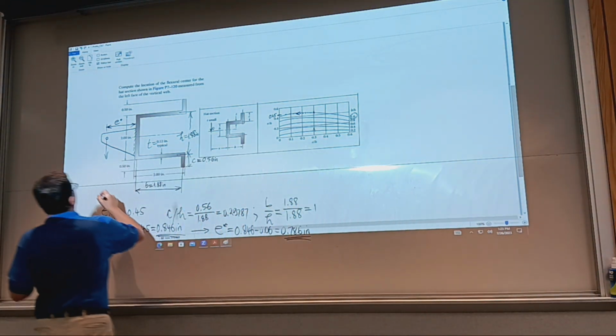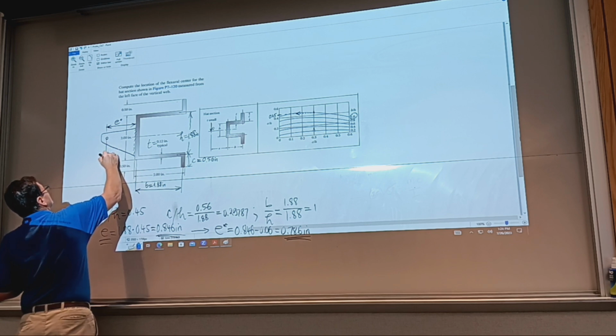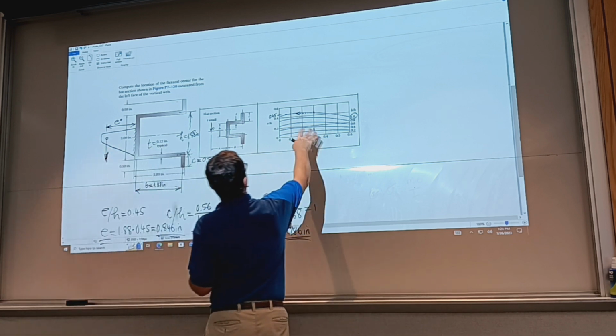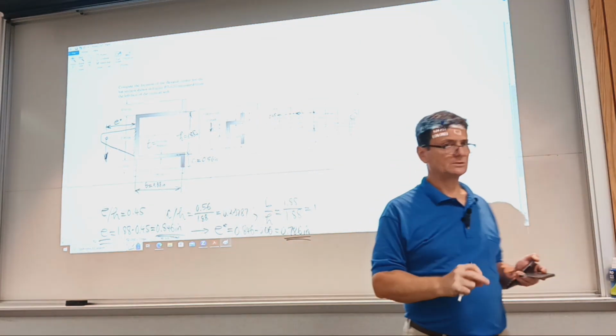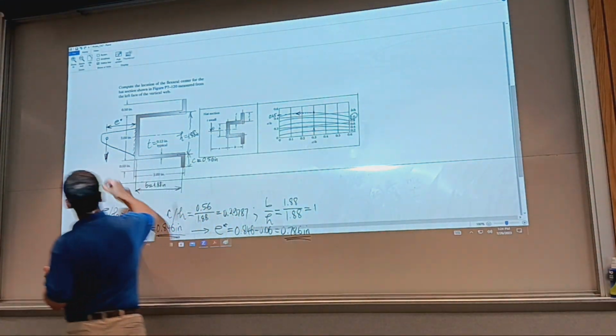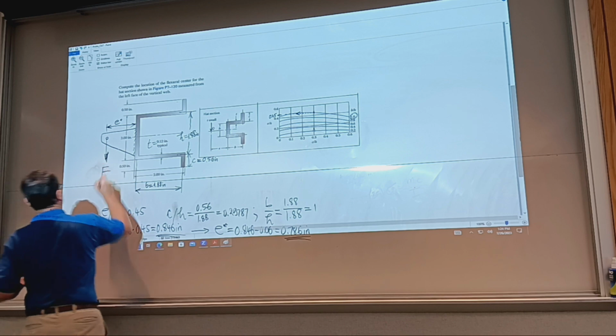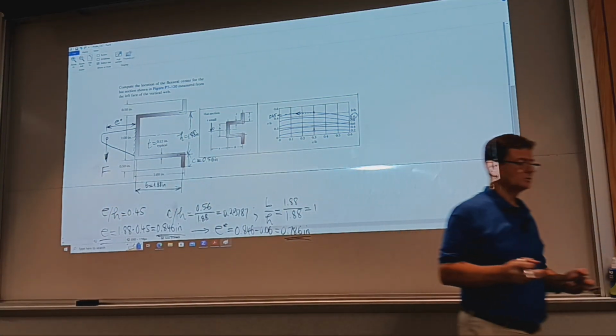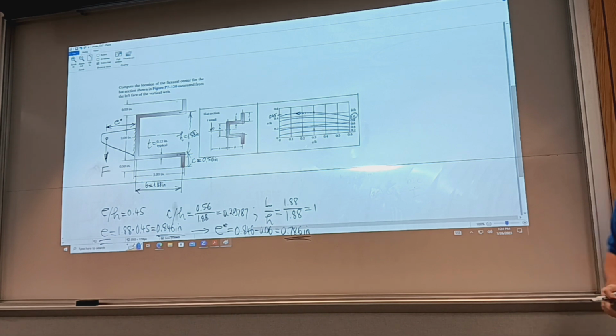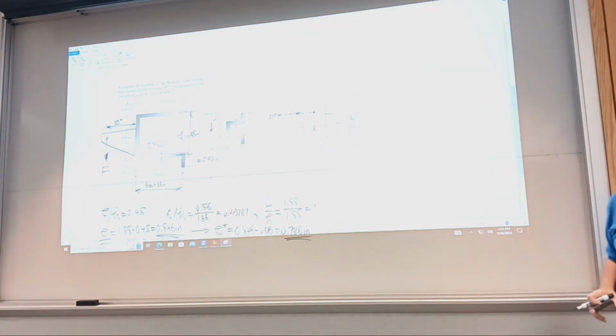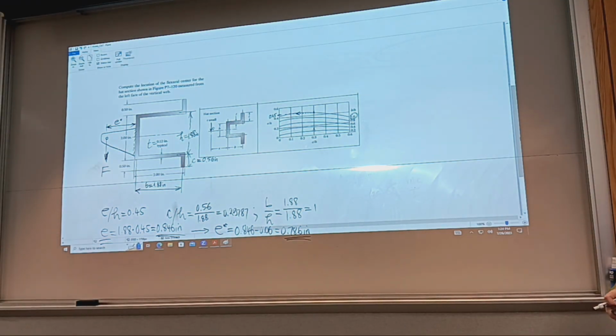Question is, do we round to a preferred size? Maybe. I mean, there are some uncertainties in using these charts anyway. Okay, so this is the load, W or F. F, we're used to using F. Was it clear? Understanding of the charts is the key to solving this kind of problems. For L-shaped channel and the split thin wall tubing, we have equations. For the lipped channel, the second last entry in table in figure 727 will likewise have parametric charts.